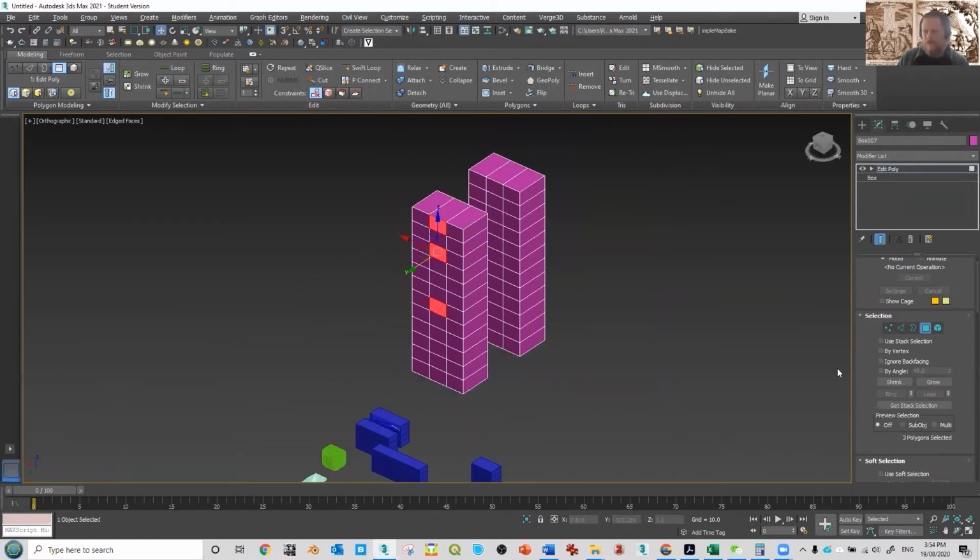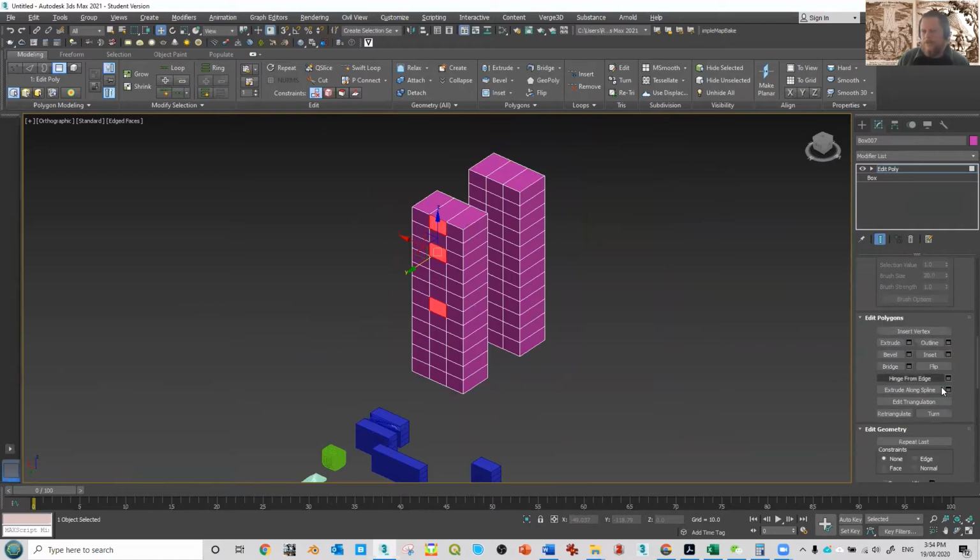I'll select some surfaces, and if I click on the extrude, this guy should come up. But if I click in here, it deselects those surfaces, so it doesn't know what to be extruding. It's probably a little unnatural in the way it feels, but it's quite useful. Is that what you mean, Jaffa?